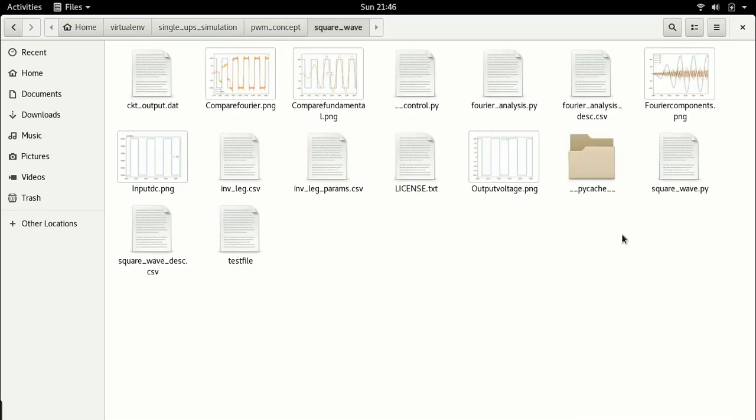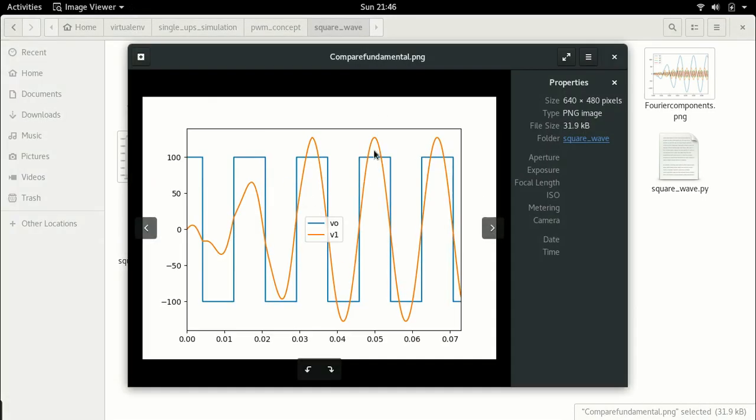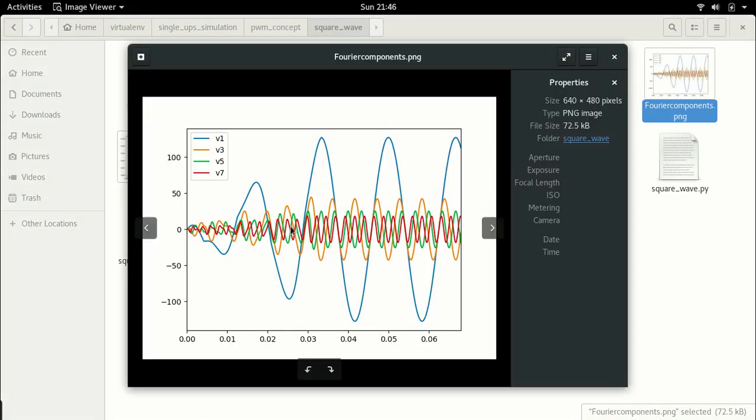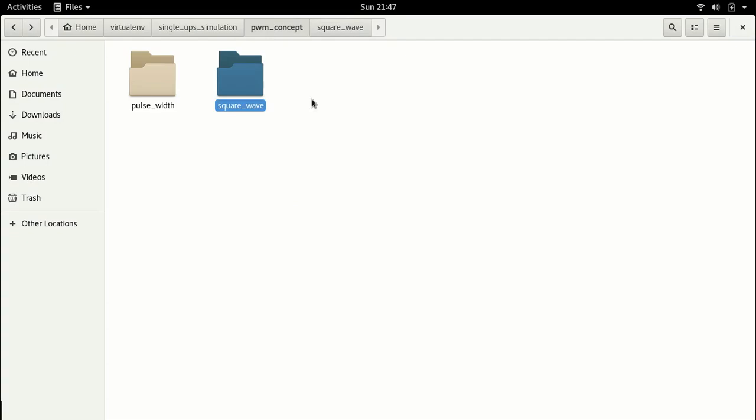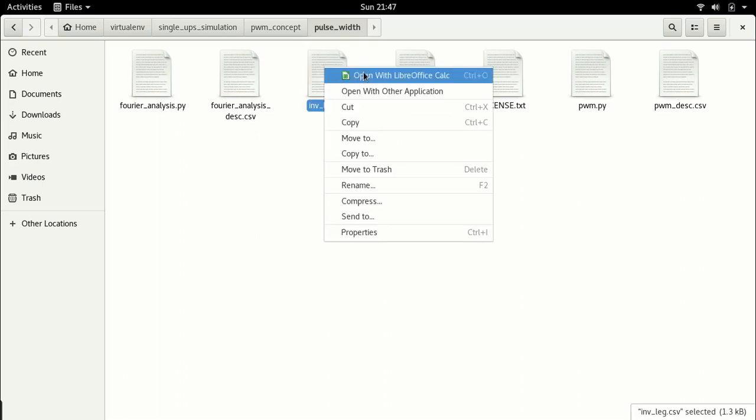So basically what I had shown was how a square wave switching can be used to achieve a square wave, or rather rectangular wave, which would result in a fundamental sinusoidal component such as this one. But unfortunately, along with the sinusoidal component there will also be several low frequency harmonics, and this is the biggest problem. So in this next lecture, I'll be talking about the next concept, which is called pulse width modulation, and how pulse width modulation produces certain improvements in terms of harmonic components. So as before, we will start off with the same model